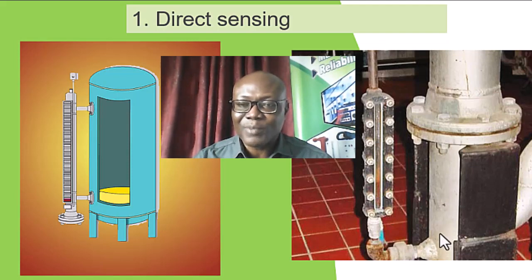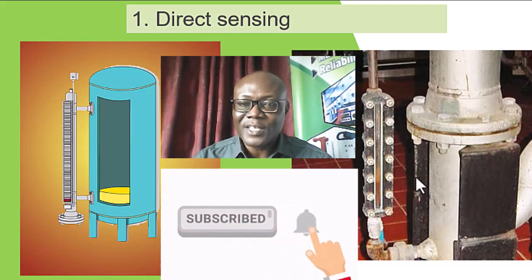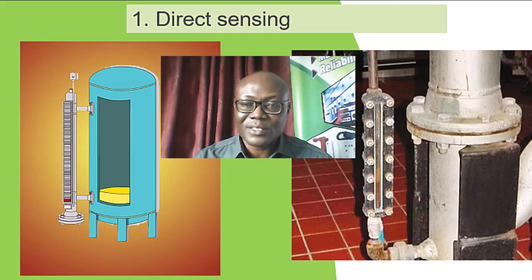It represents this particular height of the vessel. So let's assume it's 2 feet here now, 30 centimeters here, then here will be calibrated 30 centimeters. Or if from the bottom to the top of this vessel is, say, 100 centimeters as an example, okay, or 30 inches, here to here will also be 30 inches.